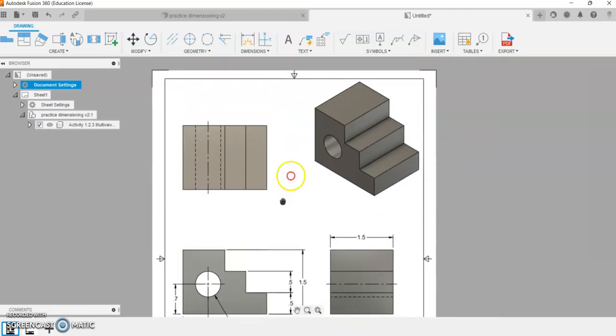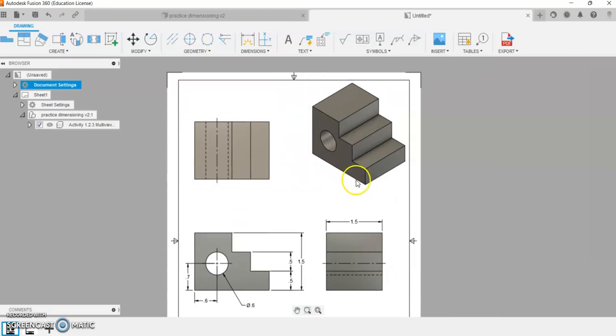So let's go ahead and do length now. Length would technically be this right here, so this measurement. I'm going to do it from my top view. I'm going to reactivate my dimensioning tool, hit D on my keyboard. I need a total dimension. That's always going to be the one furthest away. And notice how that goes right up from there. And from here, I think I'm going to do this one because it gives me a reference for where this line is.